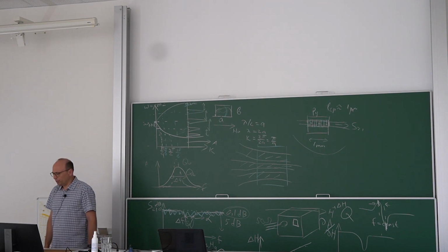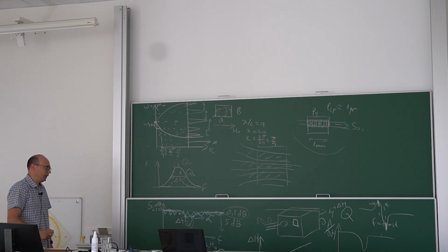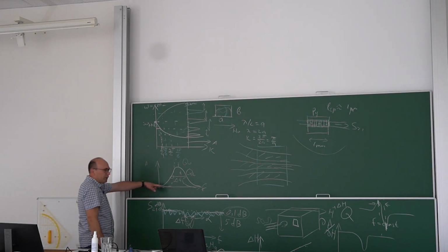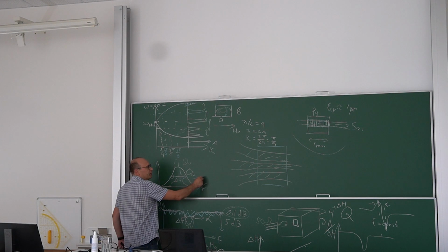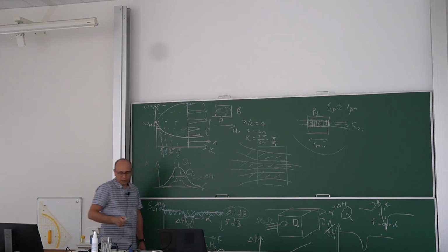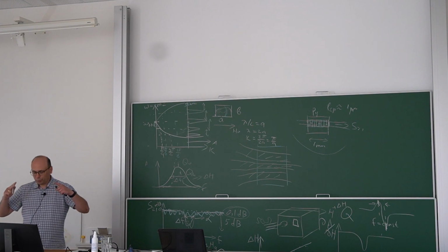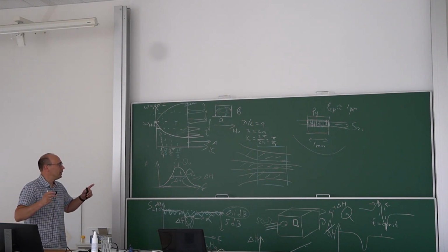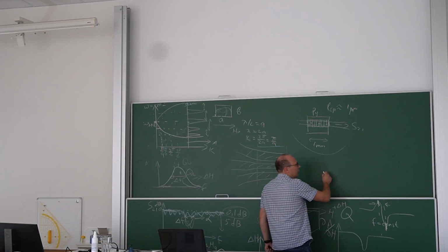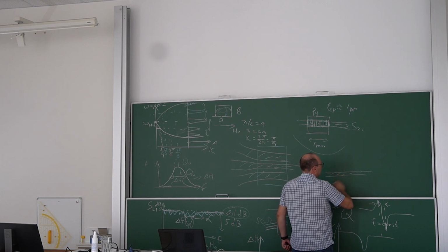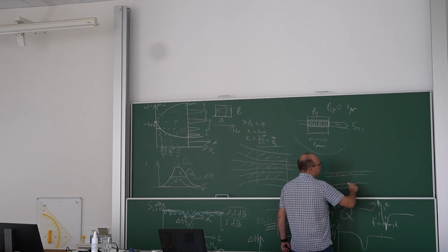So principally it's all described in any book on microwave engineering, I recommend it. And usually people speak about it just as about a resonator, but in reality, for us it's important when you perform yttrium iron garnet measurements. Principally, we don't want to measure delta H, then it will be delta F. Yes, and we're coming back to delta H at the end of the day. You don't want to measure a loaded resonator. You want to measure the original one, the real eigenvalue. And what people do for this, if you have a microstrip line, side view, yes, so 50 ohm, so some spacing and so on.